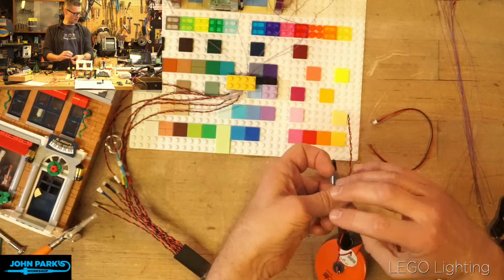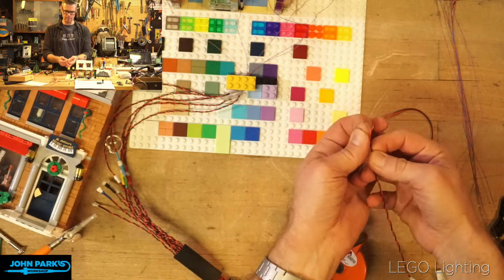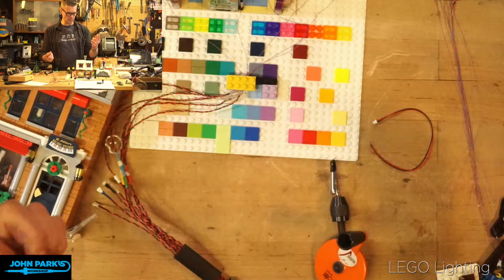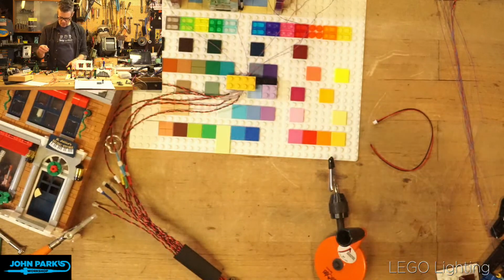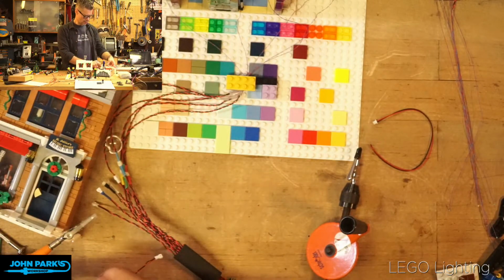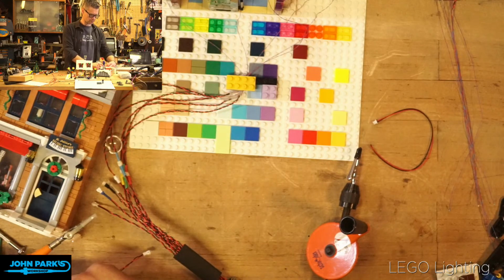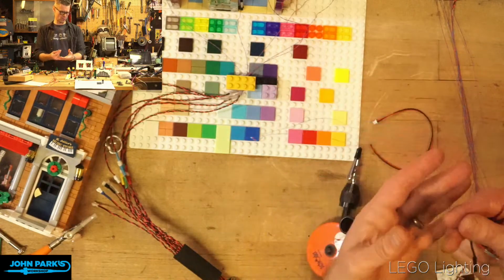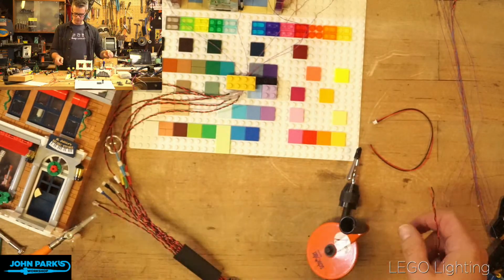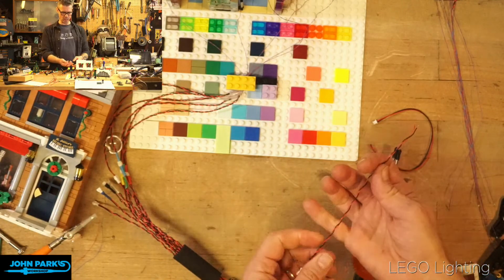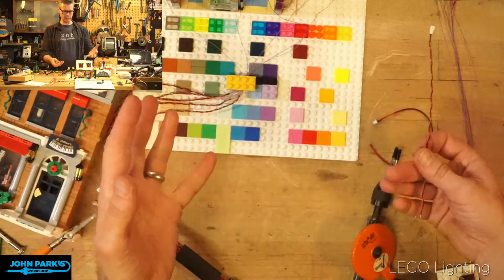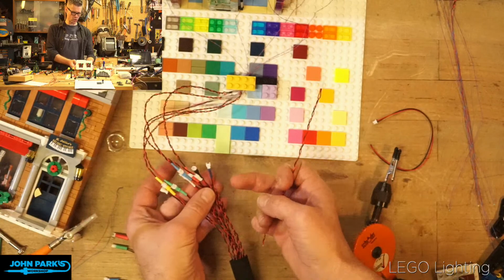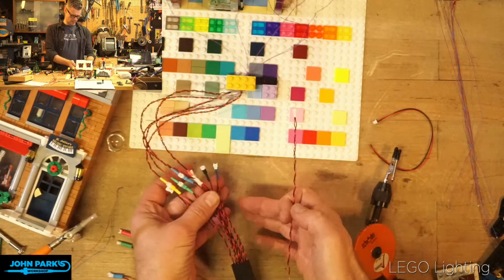So that's what I did there, and then I've got little tiny bits of heat shrink tubing I put over these, tin the ends, solder them to the LED, which I'm doing the same thing to, so you can see these LED strands. As I mentioned, they start out life as 2 strands, and I'm doing the same thing, chucking them into here and turning them to put that little twist on them. That just keeps things a little more manageable. It would look like twice as much wiring out here if I didn't do that. And then, like I said, a little heat shrink color coding on here.